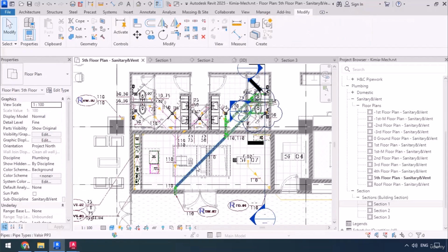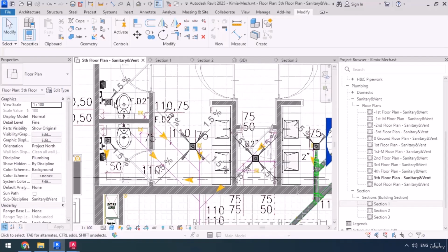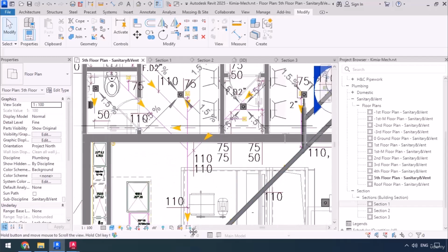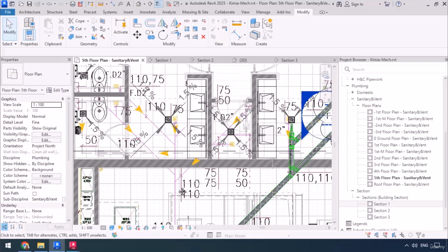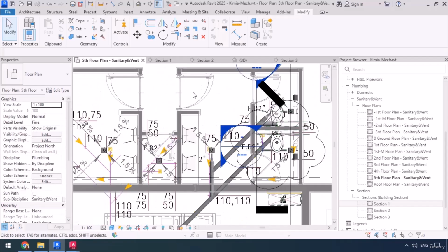Now this longer pipe that we drew at the beginning, there is a parallel of it over on this side as well. As in, we've got these floor drains, the sanitary pipes, and then a pipe that collects them all and leads them down. The sides aren't 100% the same, but they are similar enough. So I could just use the mirror command, as in we could just select this whole thing here, and then mirror the items that we've just modeled on the left side, and then we could readjust the elevations if needed.